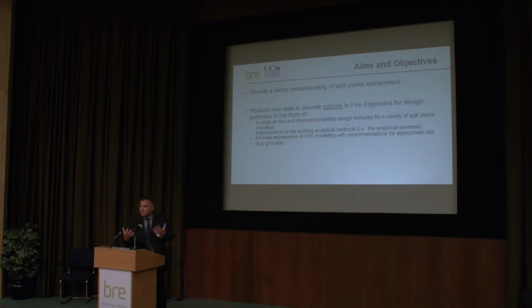But the objective was also to provide new data from an extensive number of experiments, and to provide options to fire engineers in spill plume design. So I've looked to develop a range of new and improved simplified formulae for a variety of different spill plume scenarios, and improvements to the existing analytical methods, as they use empirical elements in terms of the entrainment coefficients. I also carried out an initial assessment of CFD modeling and recommendations for appropriate grid design for fire engineers as well. So I'll be touching on these points today, but in the 20 minutes I've got, I simply can't go into any great detail.